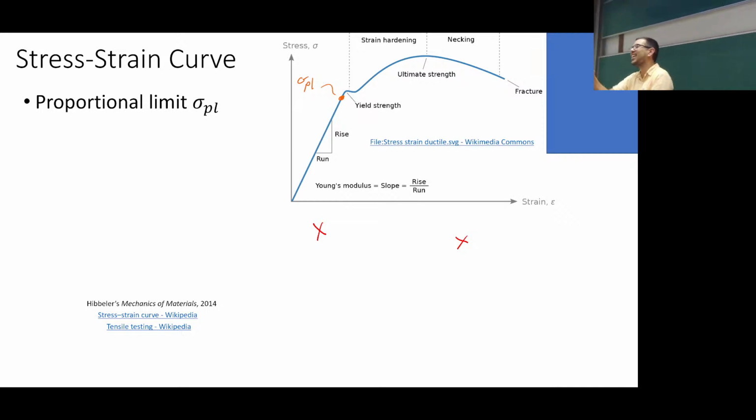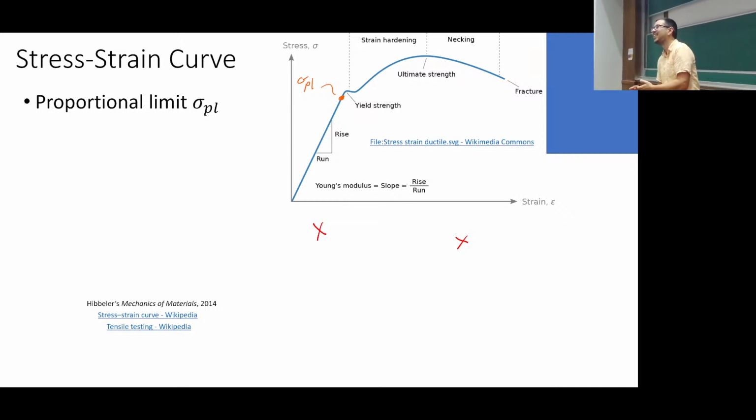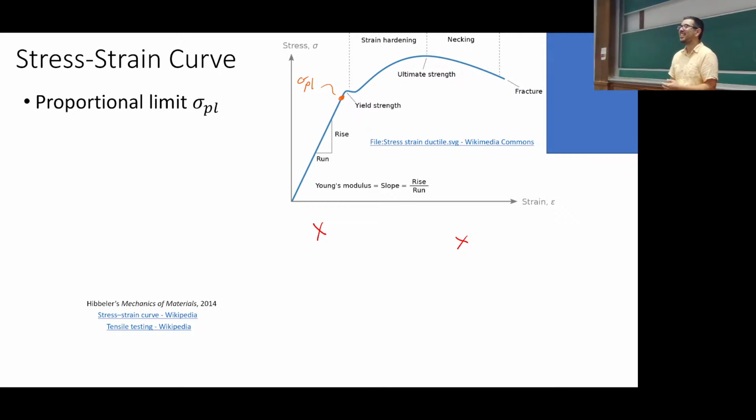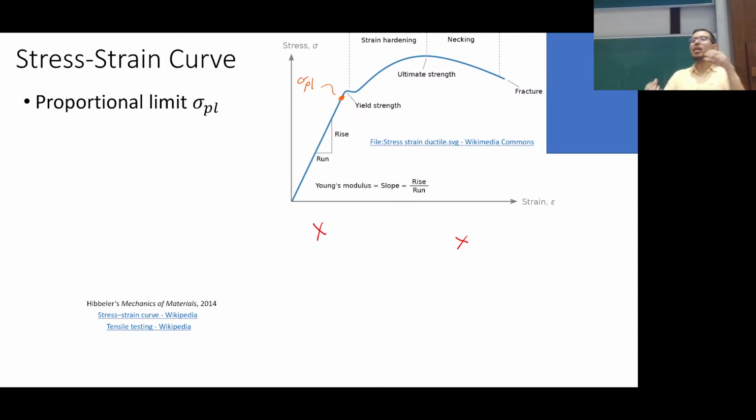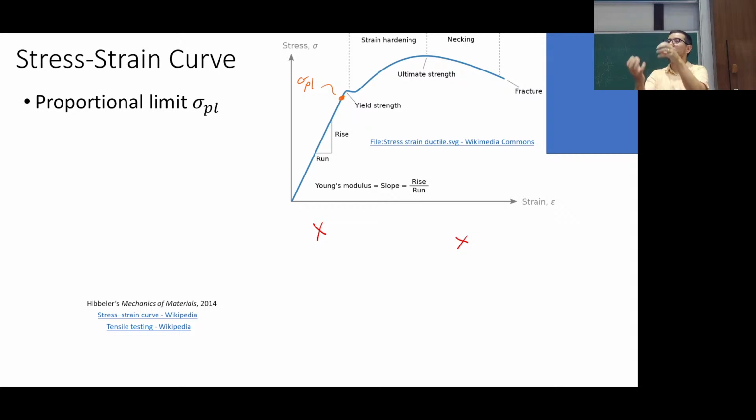Back in high school, I took a class where someone built structures out of some sort of wood, and then we would try to test the strength of it. If you don't have a really expensive machine, you can get some pretty good ideas by just using dead weights. Make the cross section small enough and then hang weights.